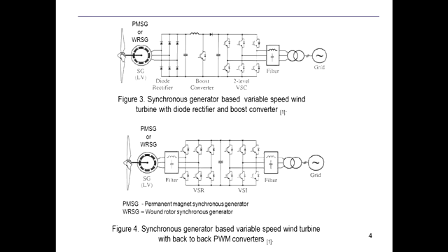Similarly, this rectifier should extract power from here, all right? But the requirement here is to produce a unity power factor situation here. That means the voltage and current would be in phase and sinusoidal. That is not possible in this case, all right? This machine or this generator will not operate at close to unity power factor at all, all right, the power factor will be quite poor.